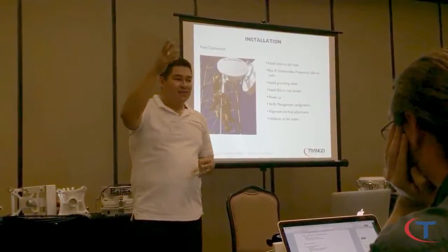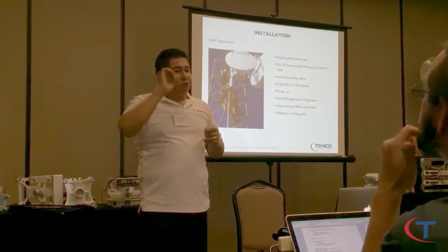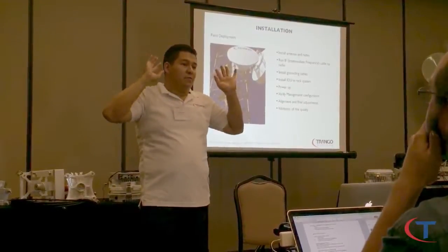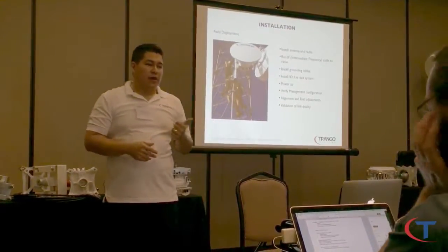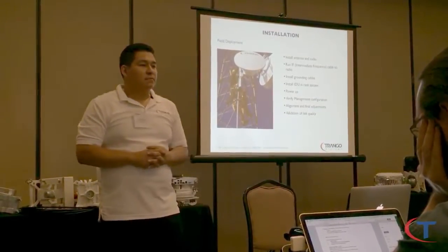So if it gets hit by any reason, by lightning, instead of coming down, a gas tube is going to blow it up and it's going to stop it. So grounding the ODU, and a polyphaser. That's what you better want. Okay? Polyphaser is designed strictly for lightning strikes.